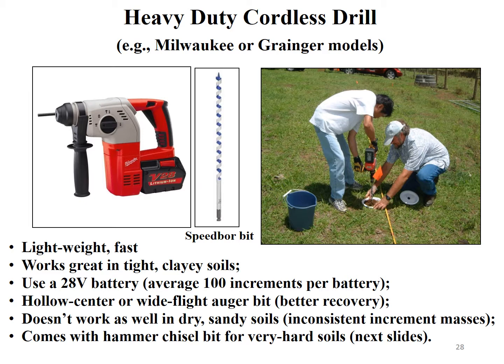In the illustration there, we've simply taken paper plates and cut a 1-inch hole in the plate and put the drill down through the hole in the paper plate, and then as you drill down to a designated depth, it's bringing up the sample out of that drill core on its veins up onto the paper plate. Then that's tossed in your sample container, in this case the bucket there on the left.